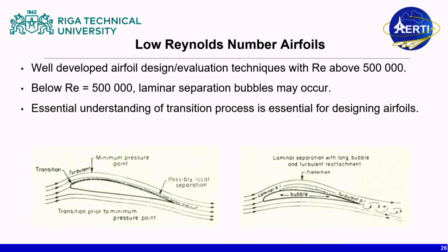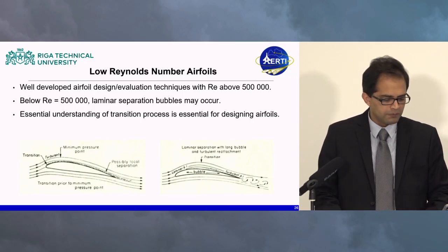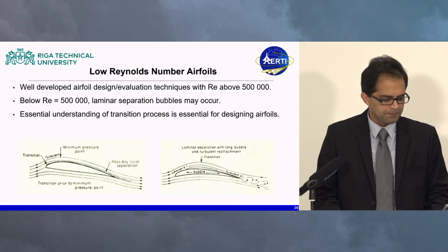The designs of high-speed aerofoils are well developed. But when we talk about the low-speed aerofoil, there are some problems related to the viscosity of the flow and the laminar flow separation, which is generated always at the surface of the aerofoil, and because of that, the performance and sustainability of the aerofoil is always affected.